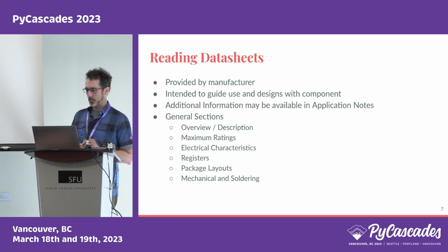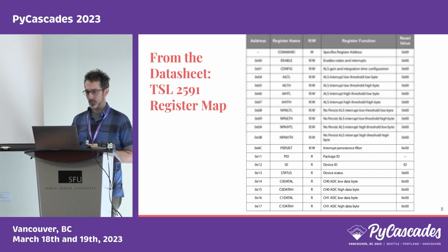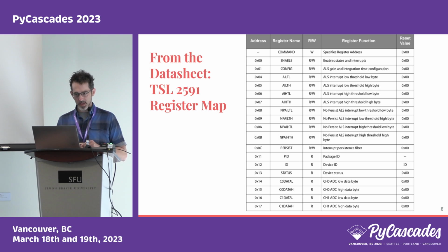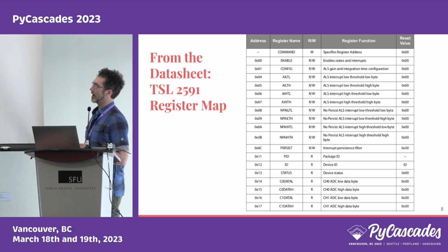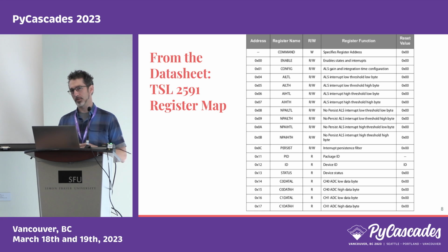But the most important thing for what we're talking about today is the register addresses and how to program it. So, this is the page out of the datasheet for the TSL2591 that lists all of the registers and what they do. So you've got a numerical address, and I should pause here and say that in I2C, addresses both on the bus and in the registers are all noted in hexadecimal, so I will be using that terminology.